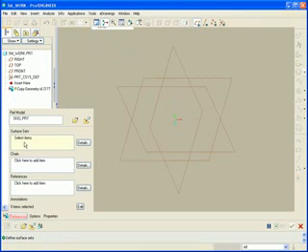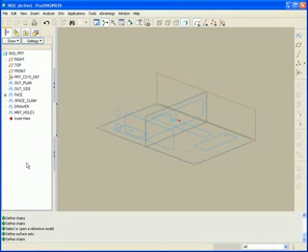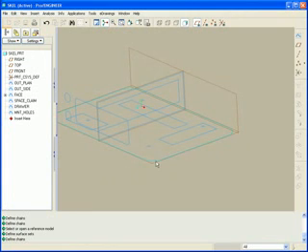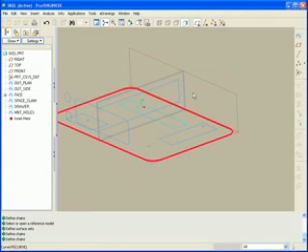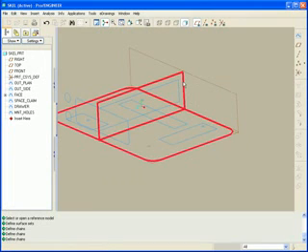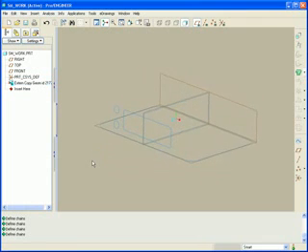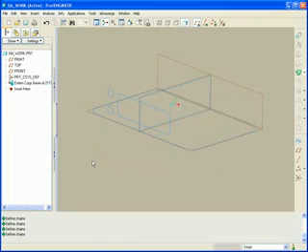So what we're going to choose in this case is to grab chains of our skeleton. So here's our skeleton, and what we're going to grab is the outside shape. We'll grab maybe the outside from the plan view, and we'll grab some of these face curves as well. Middle mouse button, and we've now completed our external copy geom. So we've grabbed a couple of relative references from an external model, which might be a skeleton. So let's start building some sheet metal stuff.